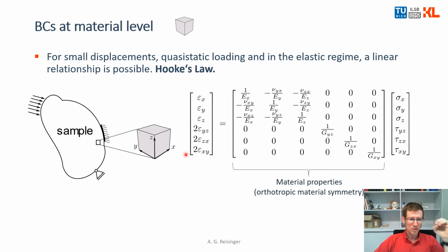at a certain point. So imagine you have some glass sphere, a Glaskugel, and you get to know the vector of stresses and strains at a certain point of your sample. So you would know these 12 numbers here, and you think, wow, now I can get my orthotropic stiffness values. No, you can't. Because if you write that down, this matrix multiplication, you will get 6 equations, but you have 9 unknowns. How should this work? It's not working at all.